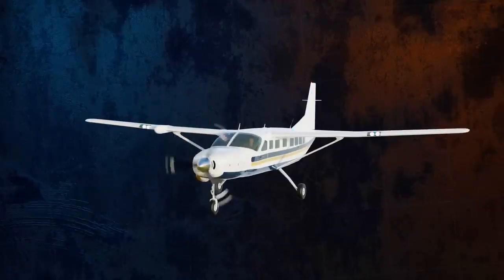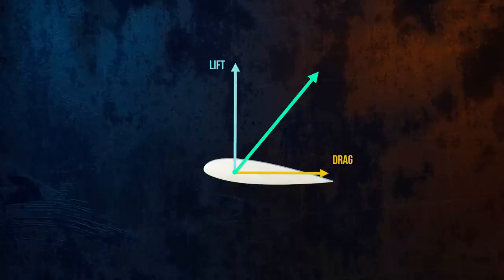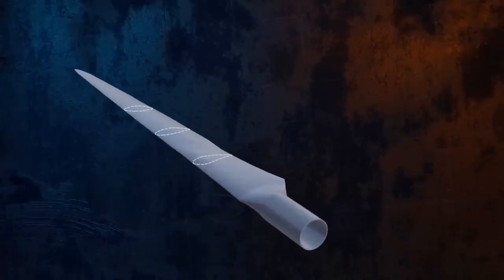When fluid flows past an object, or an object like this plane wing moves through a stationary fluid, the fluid exerts a force on the object, which can be split into a component acting in the same direction as the fluid flow, called drag, and a component acting perpendicular to the flow direction, called lift. When talking about lift, we're mostly interested in streamlined bodies like this airfoil, which are carefully designed to produce a lot of lift, but to minimize drag. Lift-producing airfoils can obviously be found in airplane wings, but also in many other applications, like wind turbine blades or propeller blades.